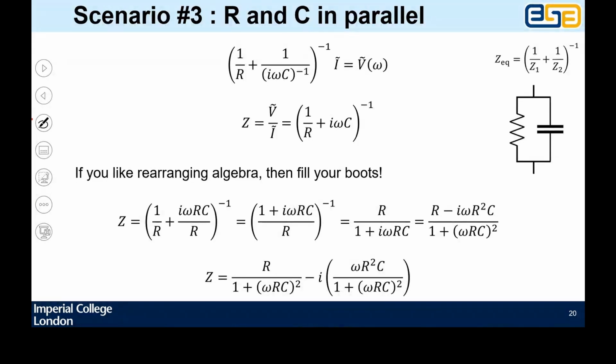So you are measuring the impedance spectrum of the bus, but in a very weird sort of 3D. You're measuring the vibrational eigenmodes of the bus. Sometimes the seats vibrate, sometimes the handrails vibrate, and they make different sounds because it's different frequencies of stimulation, all stimulated by the engine of the bus rotating at different speeds. Different bits of it vibrate at different speeds. That's exactly what you're doing when you're doing impedance on a battery: at different speeds of stimulation, you can ring characteristic vibrational modes inside your battery.